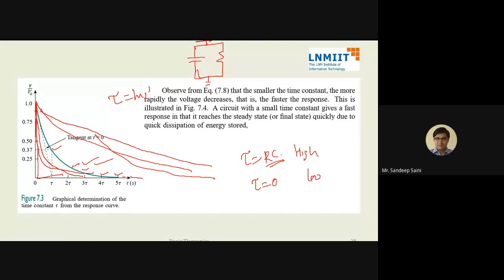This is what we do whenever you deal with capacitors. The best thing is you take the capacitor and touch it to a metal wire or metal surface, so if there is any initial voltage stored in the capacitor, it is discharged. Because if you keep this open circuit, the capacitor will not discharge, right? Then R is equal to infinity. It will not discharge. It will keep charged. So the best thing is take the capacitor and touch both the legs with a metal plate or metal surface. So it will immediately discharge. And then you use it. Okay.